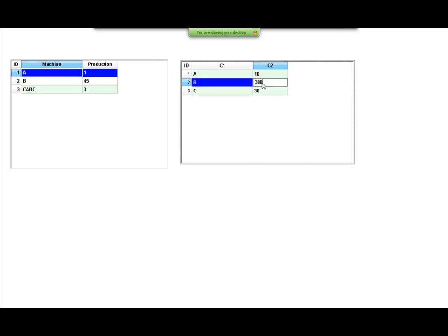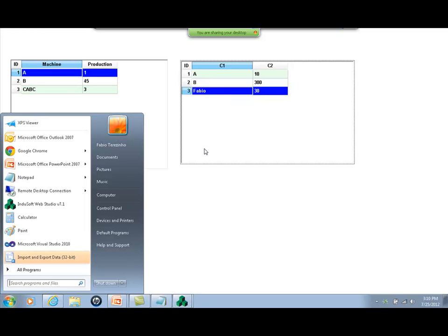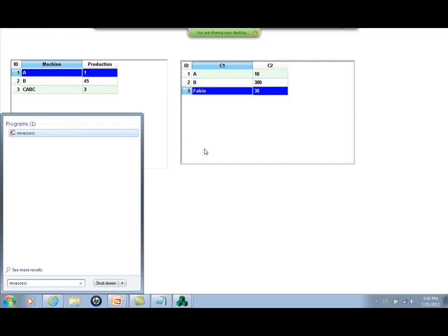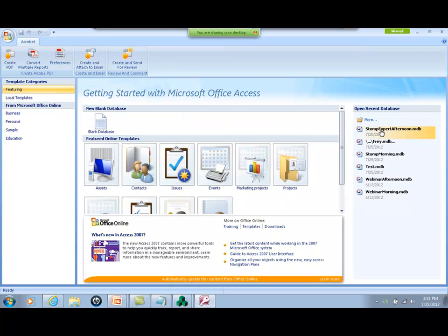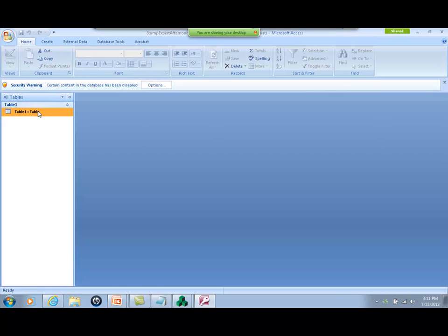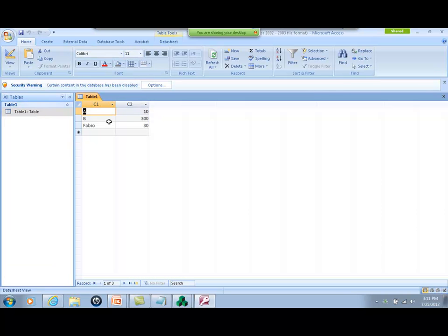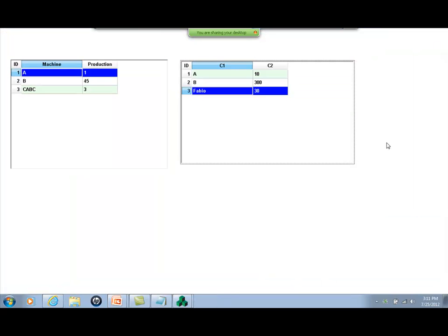And just like a CSV file, I can click here, write data into the database. And if I go back there to open the database with Microsoft Access, sorry, you would see the updated values. So IndoSoft is truly reading and writing data from this database without any scripting. All you have to do is configure the objects and fill in the blanks.